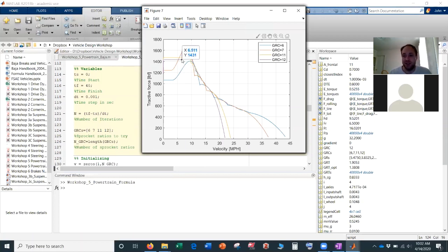Interestingly enough, you see that you actually shift before you engage. And when you shift, you change the rotational inertia. So when you do your first shift here, all of a sudden your car gets a little bit lighter, essentially. That allows you to accelerate a little bit harder, which puts more force, more downforce, on your back wheels, which allows you to get a little bit more traction. So it's kind of an odd effect, which maybe could be somewhat artificial, about which gear ratio you're in while you're sliding.